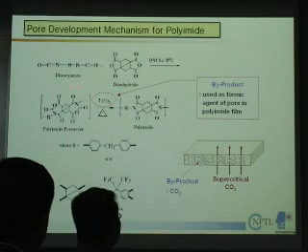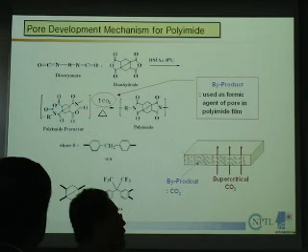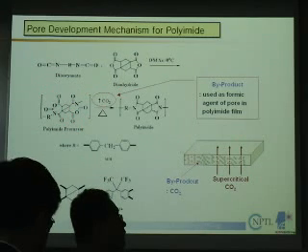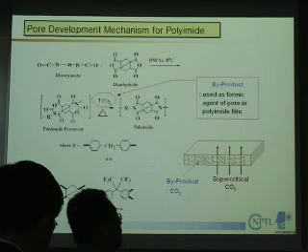So we choose diisocyanate and dianhydride in the DMAC solvent to make this polyimide precursor. Now this one you can easily apply on the system to make the casting film or whatever.